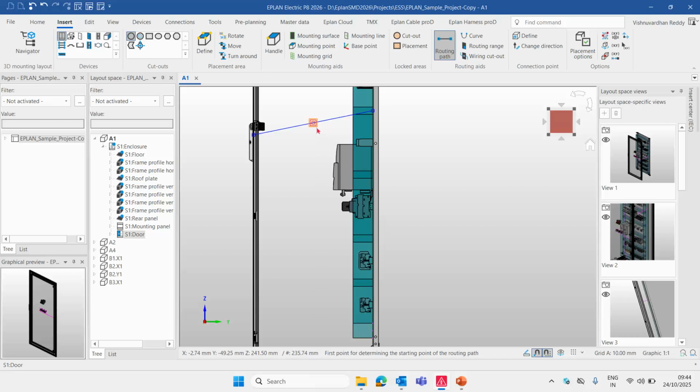Now what I did is I left the mouse. Now I am pressing enter. Okay, this is very, very important. Press enter and then you go to shift and you press less than. Once you get a different direction, again you press shift less than, it will give you a left and right. Again you press shift and less than. Now you are getting up and down. This is what I was looking for. So now I'll remove my hand from the shift and I'll go back to my mouse.